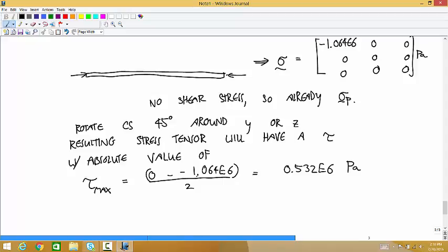In the solutions, you had that number 1 and number 2 would have the same results, but would it give you different results since they have different cross-sectional areas? They do? Then yes, they'd have different stresses. They would have the same internal loads, but then you divide those internal loads by different areas.